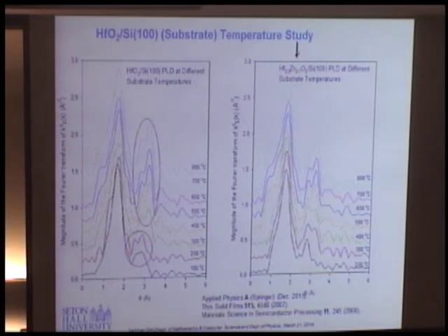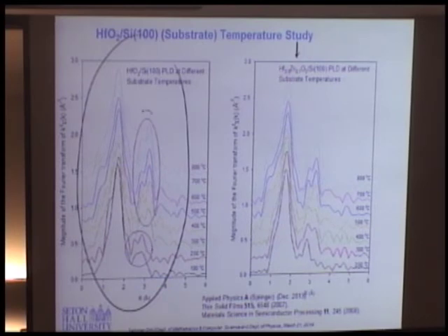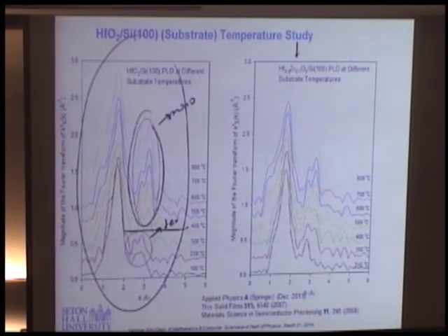Okay, look at this figure first. There's no zirconium. Now you see this big difference between this and this. This is monoclinic. This is tetragonal. Okay, there's a phase transition happening between 300 and 400 degrees. If you do the deposition, the PLD is a kind of a magic tank, all right? If you just change the temperature of the substrate, you got a different phase. So we figured out if you just put the 350 degrees, you got the tetragonal phase. If you go beyond the 400, it's going to settle at monoclinic phase. Okay? That was the thing.